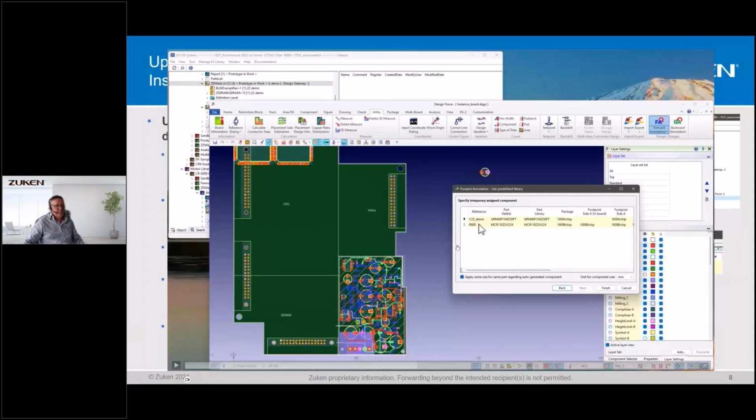We had the same message when we actually did update the module, didn't we? We made a change in the module of amplifier. We did a forward annotation to the layout module of amplifier, and we got this message. As now we updated the instance design, we also got a change, and we added C25 to the instance, and we got a change to R99, which in my instance is R800, and get this change with a new part number. So that's what we see here.